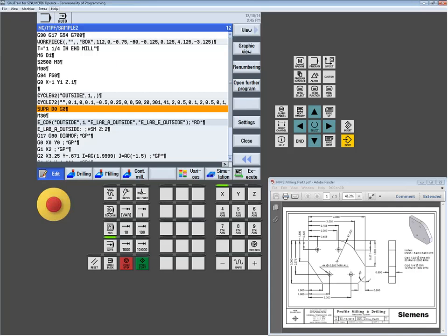And then I'm just going to make sure that I'm in a rapid mode. And now I'm basically positioning based on the machine coordinate system. So if I'm telling it Z0, you better be sure that the machine you're on has positioned the machine Z0 at the extent of the head travel all the way up. Some guys like to set it on the face of the gauge line to the top of maybe their platter. Well, now a SUPA D0, G0, Z0 just brought the spindle touching the platter. So you will have to be aware of the machine you're on when you're leveraging this command. But now the system will have retracted. I can use this for staging the table at the end of a program.